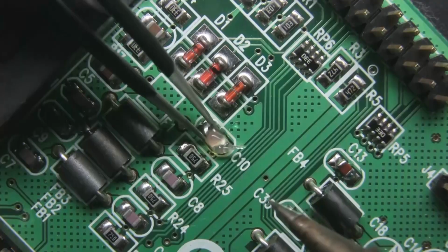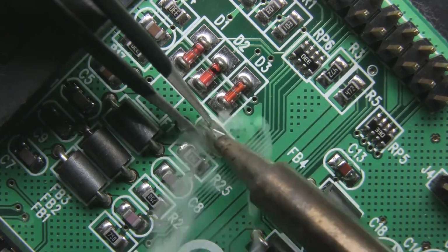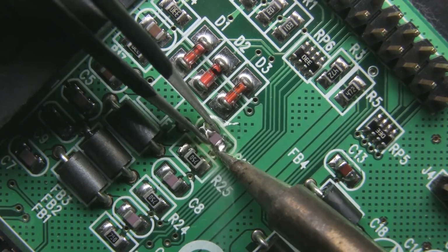a very small amount of current, which is the leakage current, flows through it, and the voltage in the reverse direction should not exceed the amount at which avalanche breakdown takes place. So, it is very important to consider the amount of voltage which is given in the reverse direction. So, PIV, or the peak inverse voltage, is the parameter which tells about the voltage which is applied in the reverse direction to the diode.